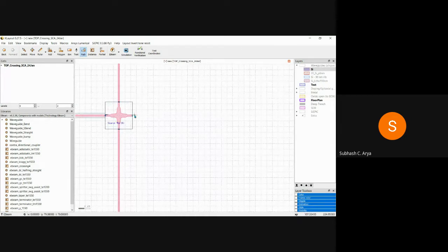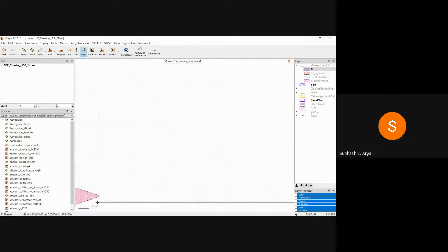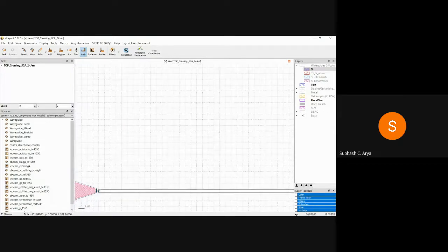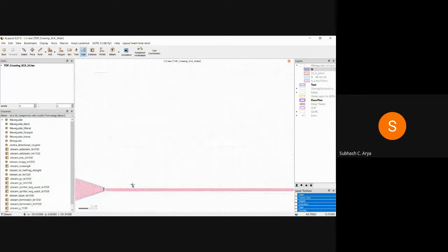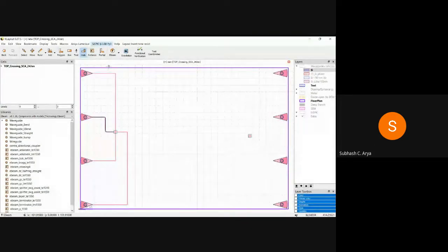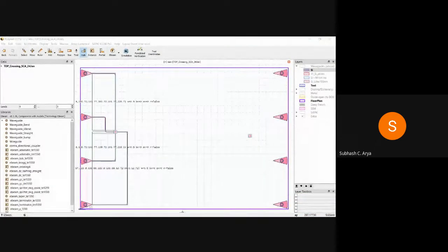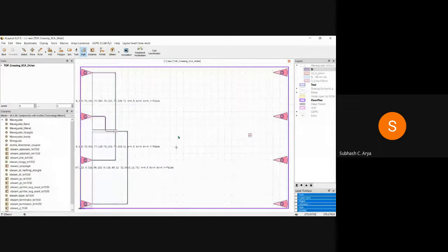Double click, and this will be last output. Let us see here. It is going to connect. Yeah, and I will go for SiEPIC waveguide, path to waveguide, and all connection has been made. So I hope you are able to see. So now going for another one.